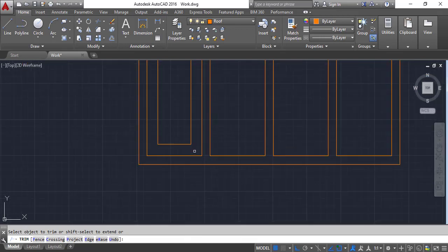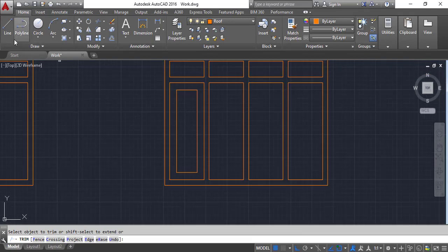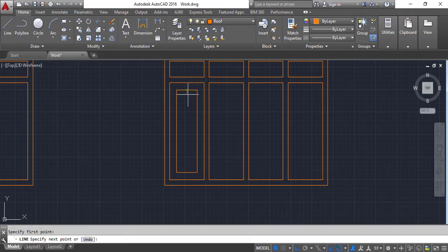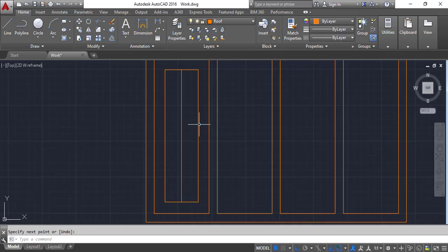This is a single panel window. If you want to cut glasses, get the line tool, you can divide this one, center, and you can divide this line to 3 or 4. This time I'm going to divide 3, using divide, and divide segments 3, enter.